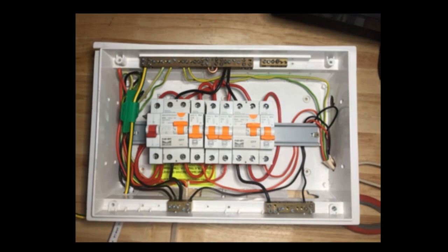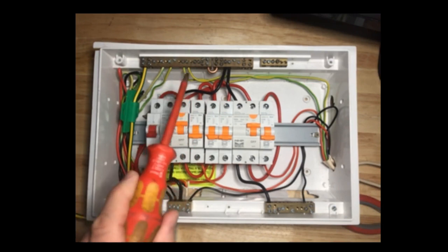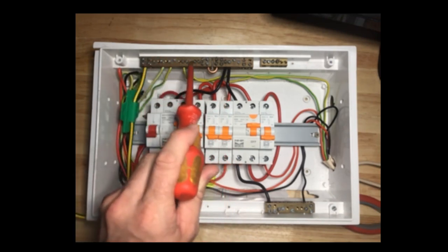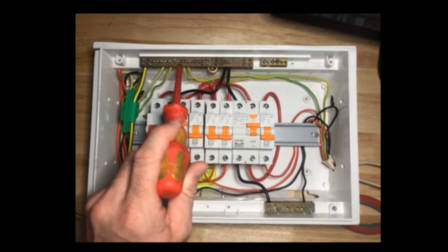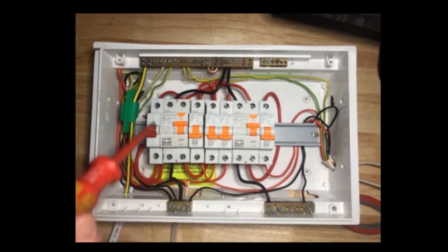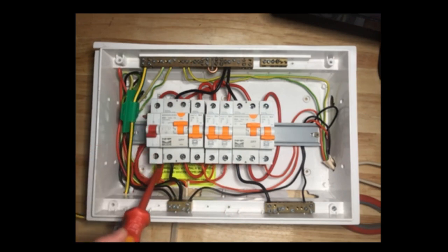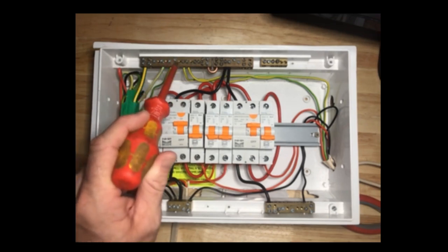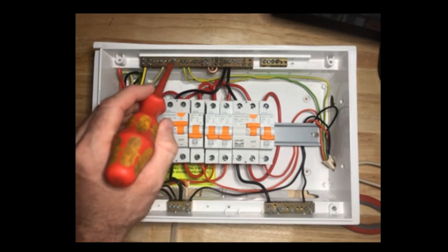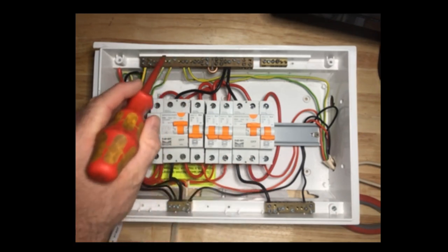The first thing that I'm going to do, remember that the standard just said that I must test between all live parts and all the earthed parts. So everything that is earthed in this installation will be connected to this bus bar, which means I need to test between that bus bar and all live parts. Everything that's live in the installation will be connected to my main incoming phase, which is connected here to this terminal of my main switch. So if I test between that terminal and the earth bus bar, I must therefore be testing between all live parts and all earthed parts, because they're all connected either here or here.